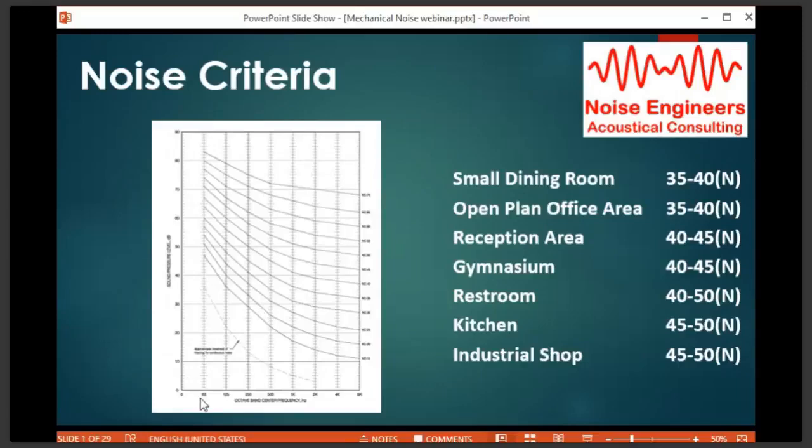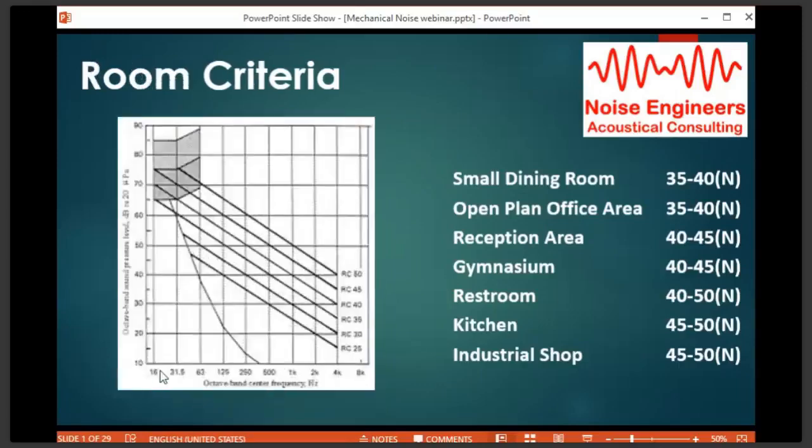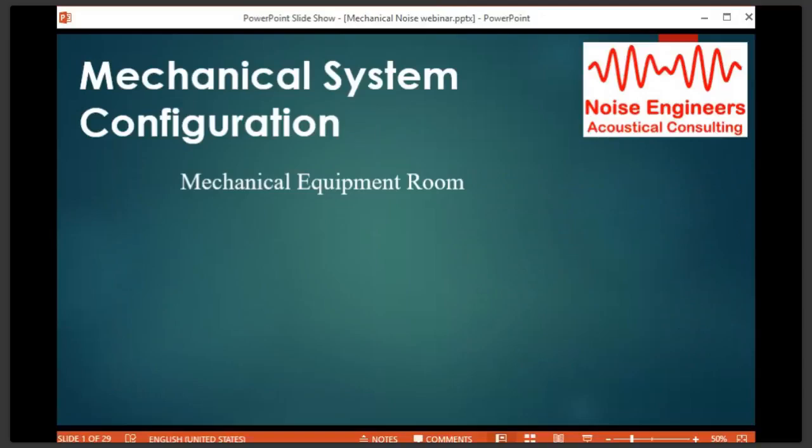One starts at 63 hertz and one goes down a lot lower, 16 hertz. Which is different than an A-weighted one, which is going to give you these aren't perceived as much, but it is an issue with HVAC equipment, that low rumble from either vibration or from breakout noise, that low frequency.